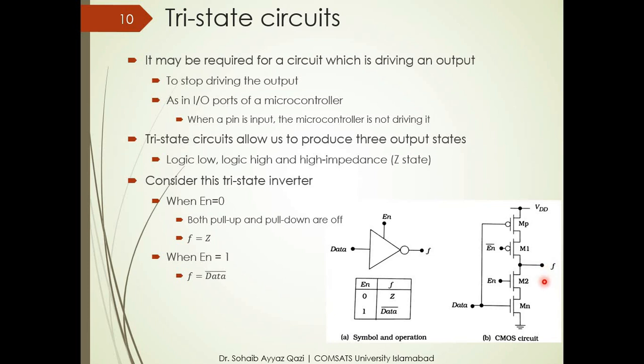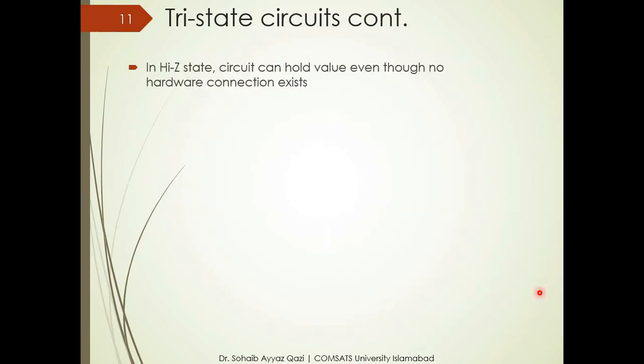In the next phase we disconnected this circuit, we isolated this terminal, and the capacitor was already charged. If this capacitor was charged, there is no direct path which can be used to discharge this capacitor. So this capacitor will hold the charge.